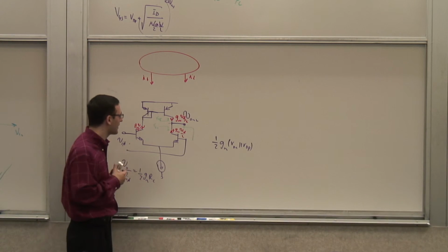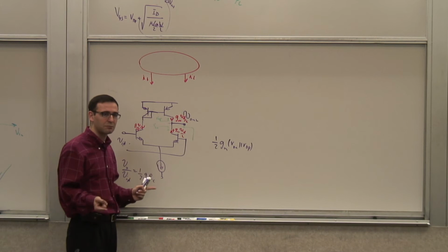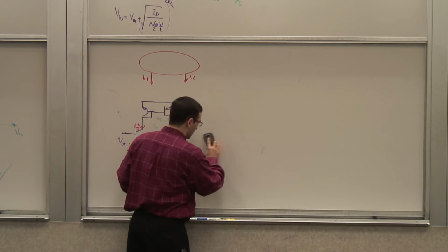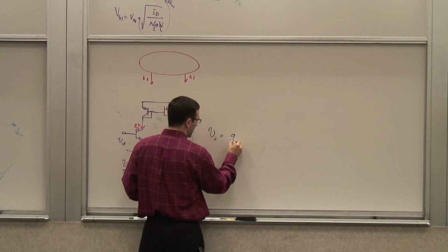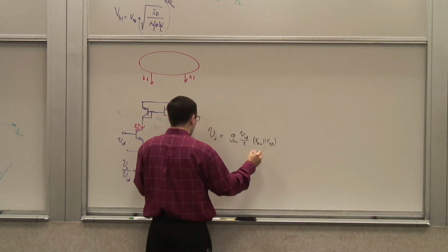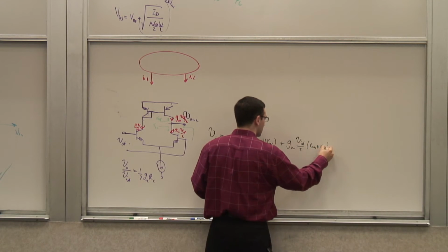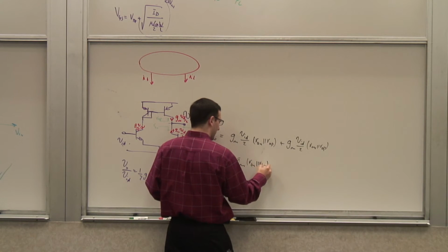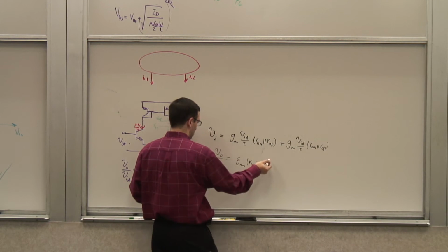Right? So if I want to determine the voltage of that node, what do I need to do? These two current sources are in effect in parallel driving that resistance, and the total resistance is RON in parallel with ROP. So in other words, you can think about it this way. VO is this contribution, which is GM VID over 2 times Rout, which is RON in parallel with ROP, plus GM VID, the upper part, over 2 RON in parallel with ROP, which gives me GM RON parallel with ROP. And if I want to calculate the gain, VO over VID, that's what it's going to be.